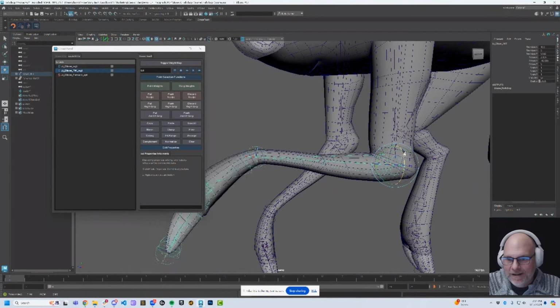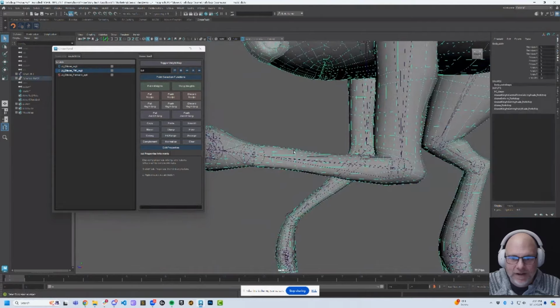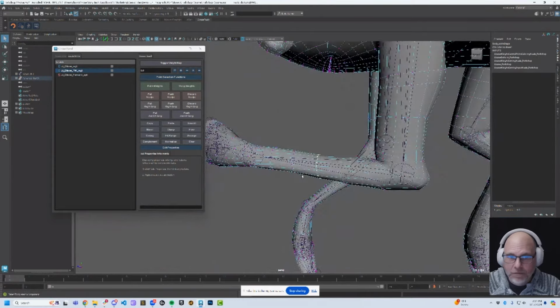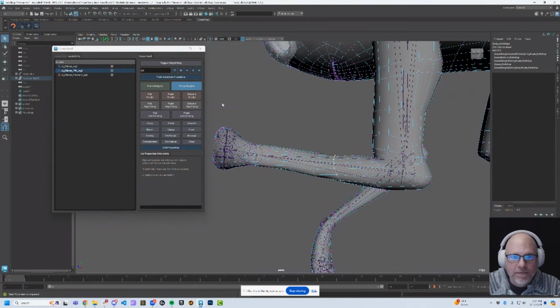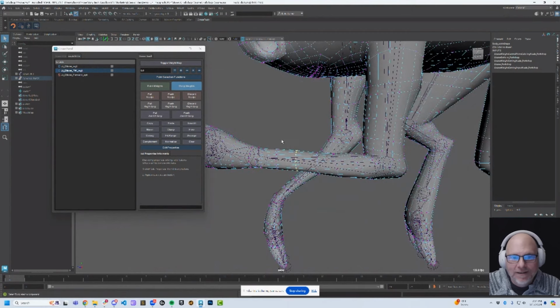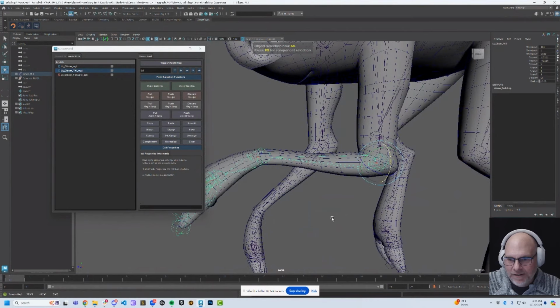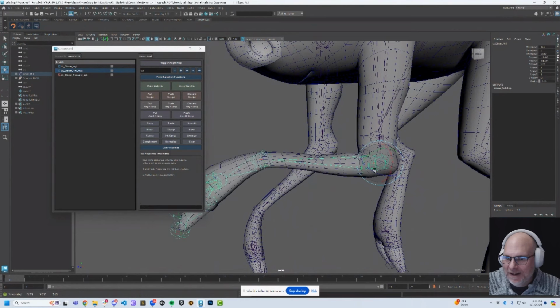So now you see, I'm twisting it, but let's say I want to change the twist weight. So I can come into this and I'm going to just start adding extra weights there. So I'm in my weight and I'm going to add weight. So I want to bring it down into the arm a bit more. All right. So I'm going to bring this into this and I'll bring this into this. Right. So now I'm introducing more twist into the arm. I'm changing the character, if you will, of the twist. So as I come through here now, it's going down more into the arm, right? But I didn't affect my up and down at all.